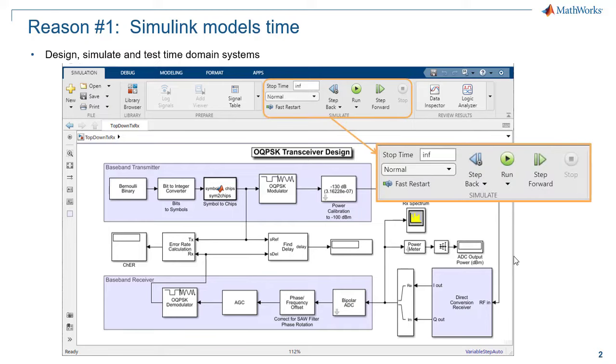While Simulink takes care of all that housekeeping behind the scenes, you have lots of control over how you want to run that simulation. Forward, backward, one step at a time, or with a variety of acceleration techniques. A side benefit of Simulink is that you can see the system architecture at a glance because of the block diagram environment. This is much harder to see in code.